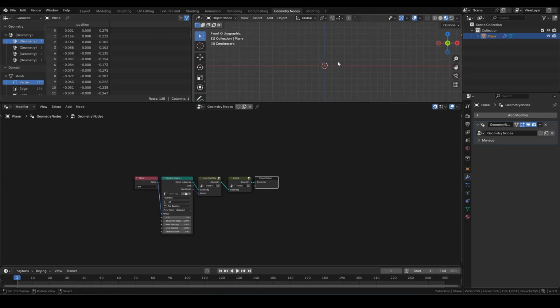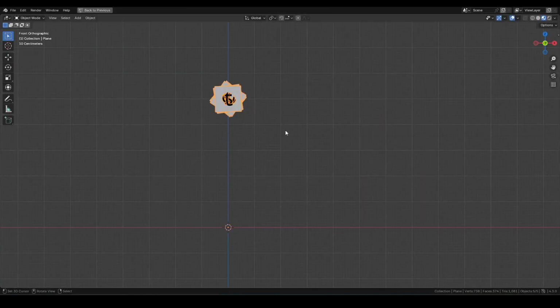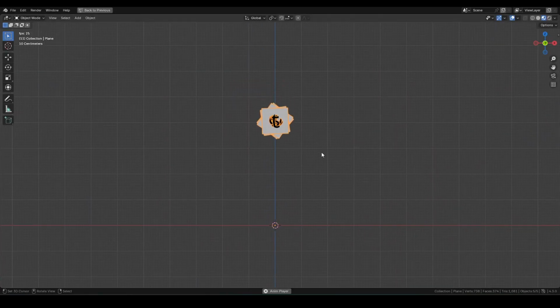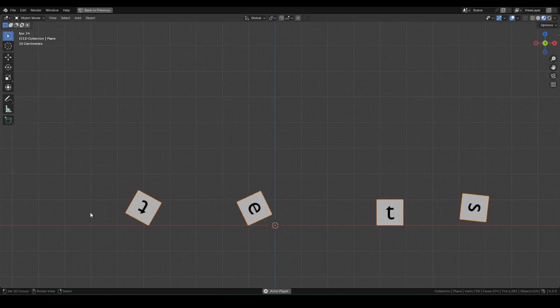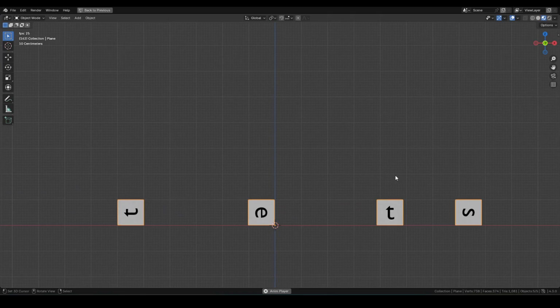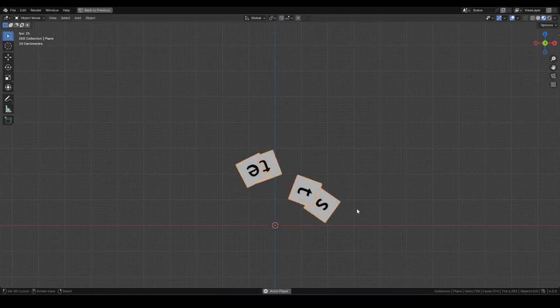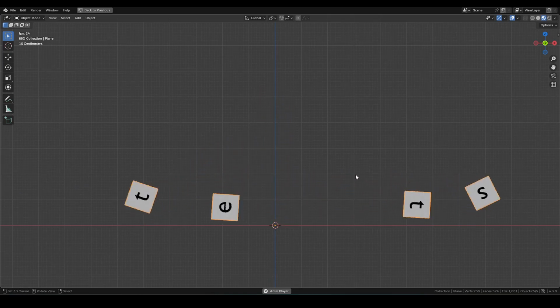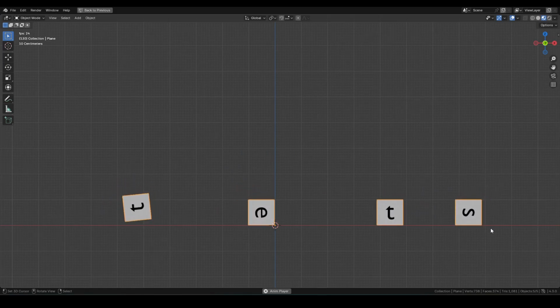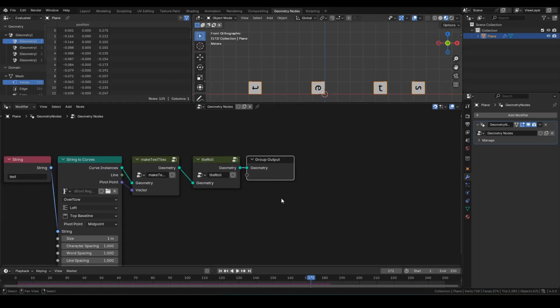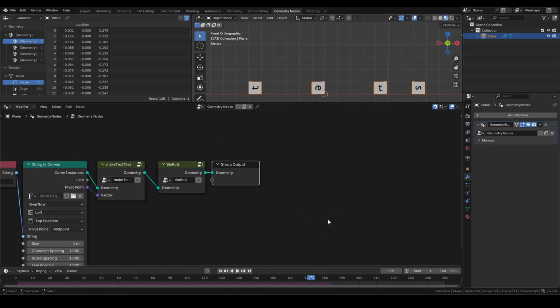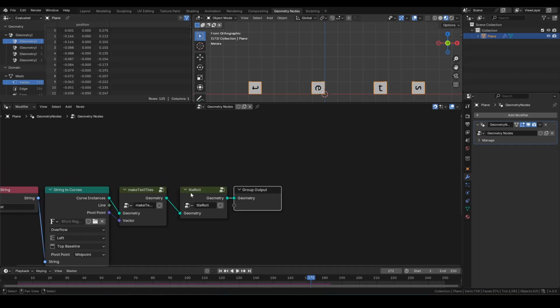All the tiles should be hovering above at initial position on frame 1. Run the animation and we now see the text tiles bouncing around as before. Since this is a text animation, we want to make sure that text tiles are readable at the end. So I'm going to use a technique I call bake and offset. We'll bake the end location and offset them from the start. To do so, we want to specify where the tiles should end up before simulation.